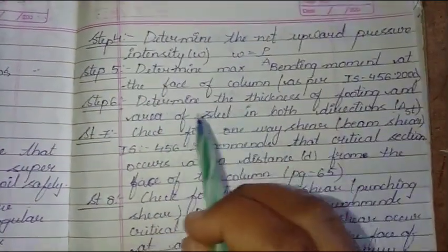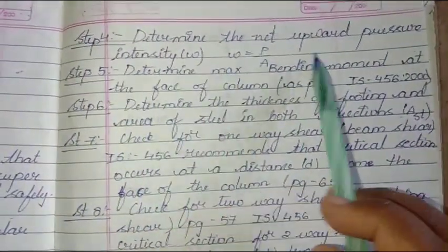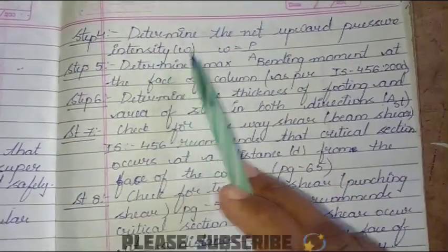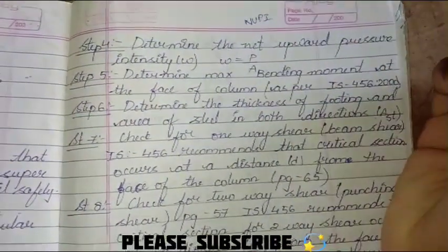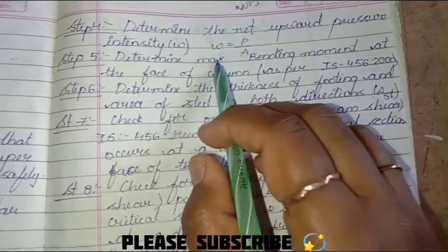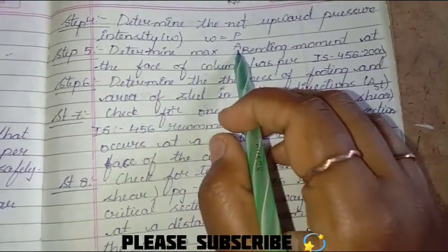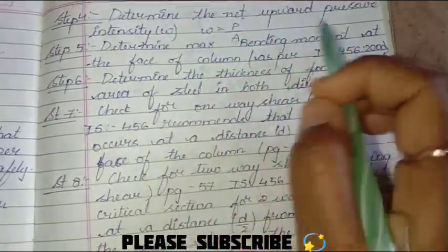So in the previous step, we decided the dimensions of the footing. Now we are determining the net upward pressure intensity. Remember, it is nothing but NUPI. We are determining it using this formula. Again, the stress is going to be the force by area. So using this, we will determine the net upward pressure intensity.